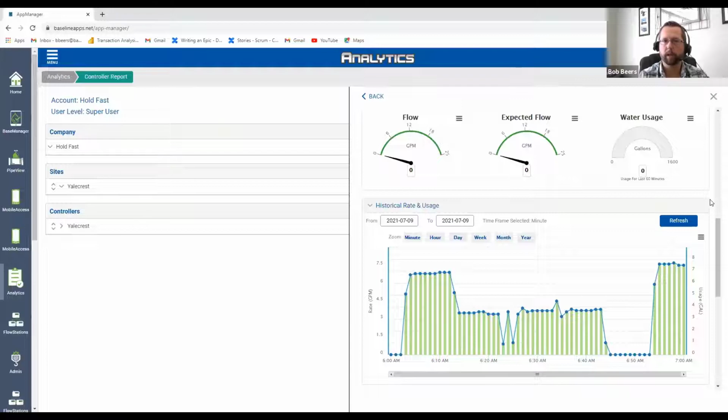So the 2-wire electrical circuit from the controller itself. It looks at that information and processes it to make real-time dynamic decisions, but we weren't storing it in a log and then pushing it up to the server. So 17.9 is what enabled that functionality. So previously we were always looking at that information from our decoders and from the 2-wire circuit itself, but 17.9 then enabled us to store the information and send it up to the server.